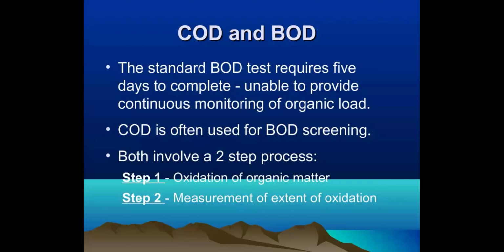COD, what does it mean? Chemical oxygen demand and BOD, the difference. COD is often used for BOD screening. Both involve a two-step process. Step 1, oxidation of organic matter. Step 2, measurement of the extent of oxidation.